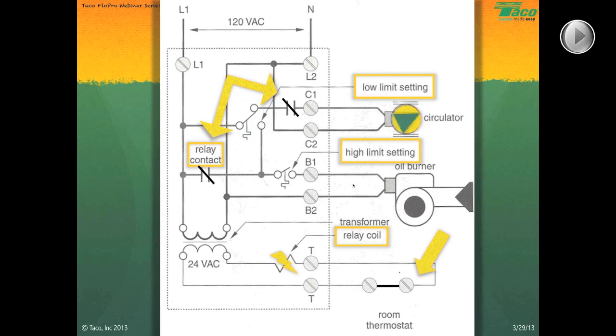Is that the best way to run that type of an operation? Well, it's the simplest, I'll give you that. It's the least expensive way to get a boiler to make domestic hot water. You don't see many new boilers with tankless coils installed in new construction installations. I think it's okay to put them in if you're swapping one out, you can replace an existing one. But new construction, you really can't do it, and it's not the most efficient way to make domestic hot water.